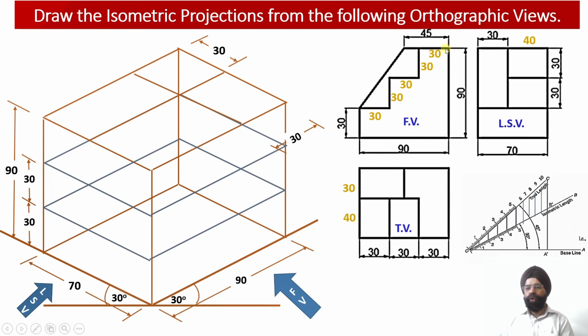So what I have to do, I have to obtain this 45 millimeter straight cross section of this particular web as it turns towards the left, towards the rear end. Please check, this is my web which is moving from the front face to the rear face, and on the rear face side, now I need to measure this distance equal to 45 millimeter. So I have marked this distance equal to 45 millimeter.